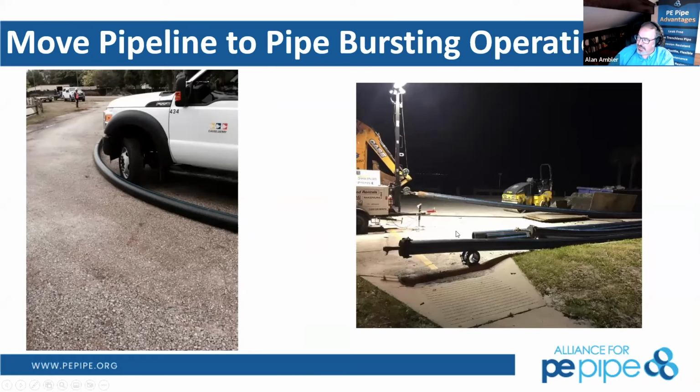So here's a laydown yard where they've directionalized this pipe up against this dumpster and used this 4x8 piece of plywood to protect it. The next night, the guys forgot the 4x8 plywood piece and subsequently gouged this pipe. I'll show you exactly that gouge in a few minutes, an example of an okay scrape and an example of a bad gouge.